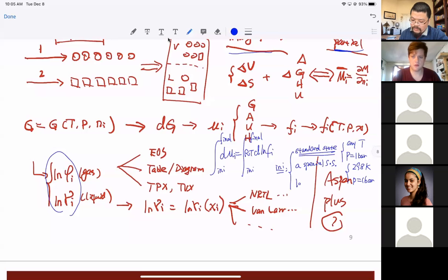If you are having low pressure, then we have our best friend, ideal gas. If you recall, we had exam problems on fugacity or chemical potential calculations from the steam table. We always look for the lowest pressure, right? 1 kPa as the actual value from the steam table.